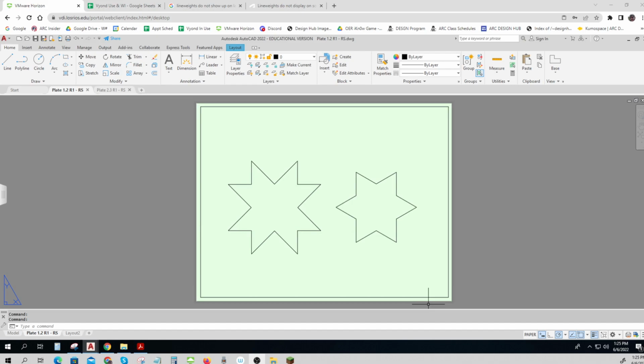One very common way to meet standards is to group lines together that serve the same look or the same function or represent the same object. So we're going to look at one of the ways that you can do that using something called layers. Layers allow you to group things together and you can make them show or not show all sorts of different things, but you can make those changes to everything on that layer all at once. So let's take a look at the mechanics of making layers.